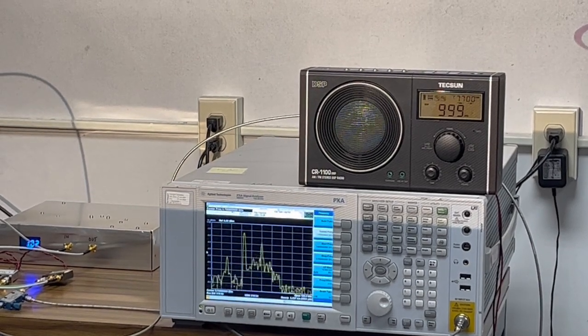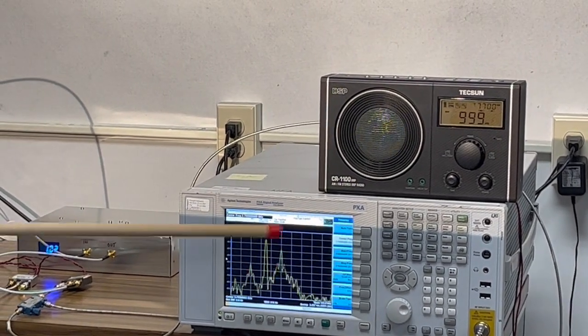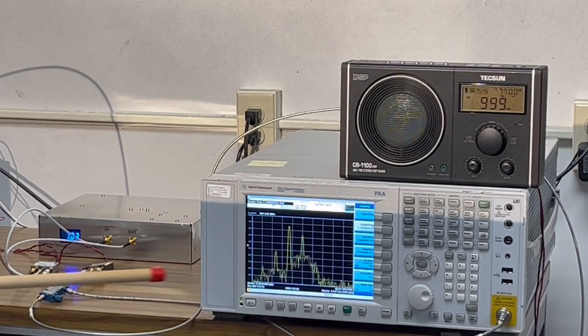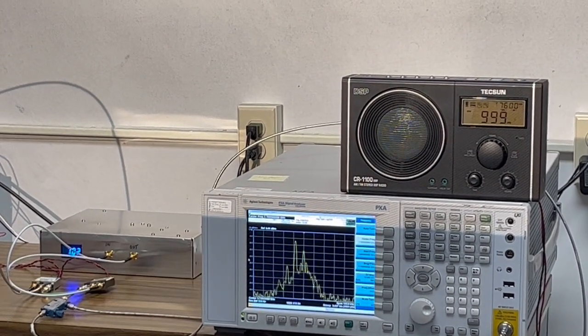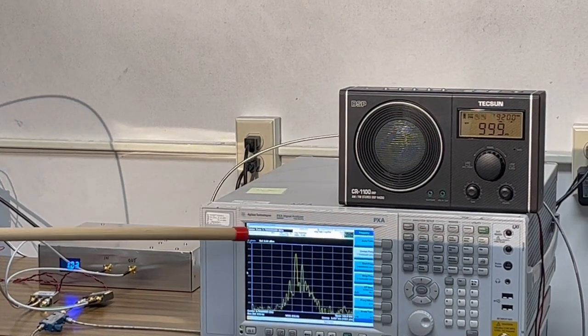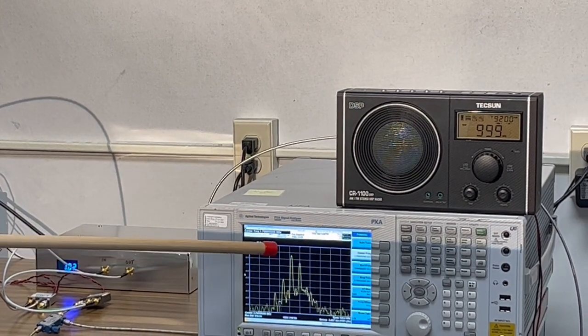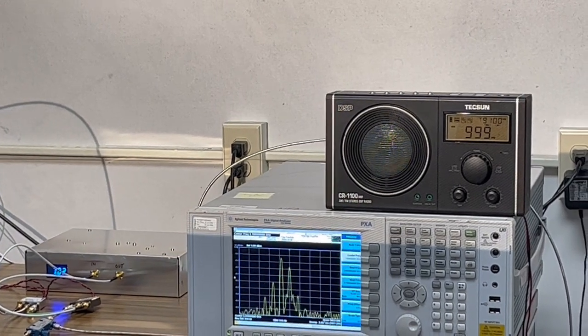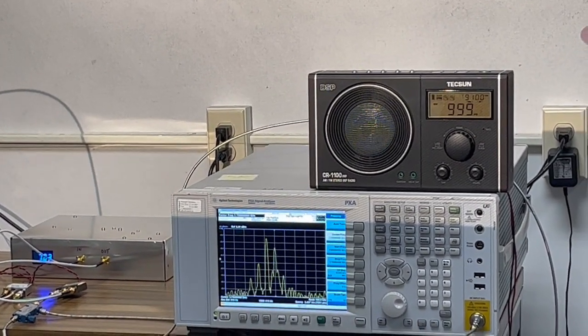But now I'm going to move it around. See it moving around and leaving the signal of interest frequency alone, moving around the interfering frequency. And when I get too close, there, it prevents us from hearing the signal of interest. Instead, we hear this audio tone that's at the difference frequency. See, it goes down as I get closer and up as I don't know if you can hear that on the film. So that's problematic, like I said.